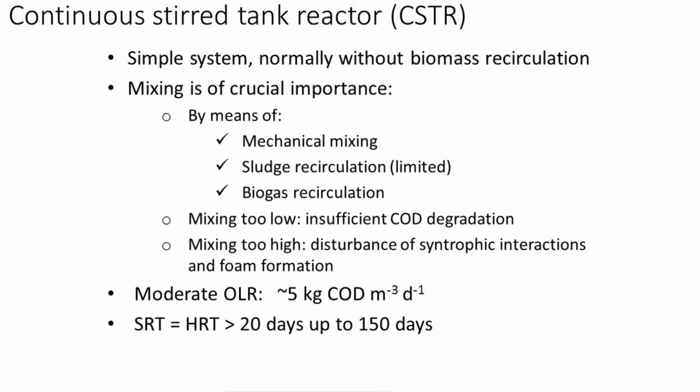So there's some thinking on how to stir that system, but in general, it's quite simple. The mixing, make sure you mix enough. If it's too high, you're really going to cause a lot of shear, you're going to make foam, and it costs you a lot of energy. If you don't mix enough, everything is unevenly distributed, and I will not have good methanogenesis in this reactor either. They have moderate loading rates because they're not super well mixed and controlled.